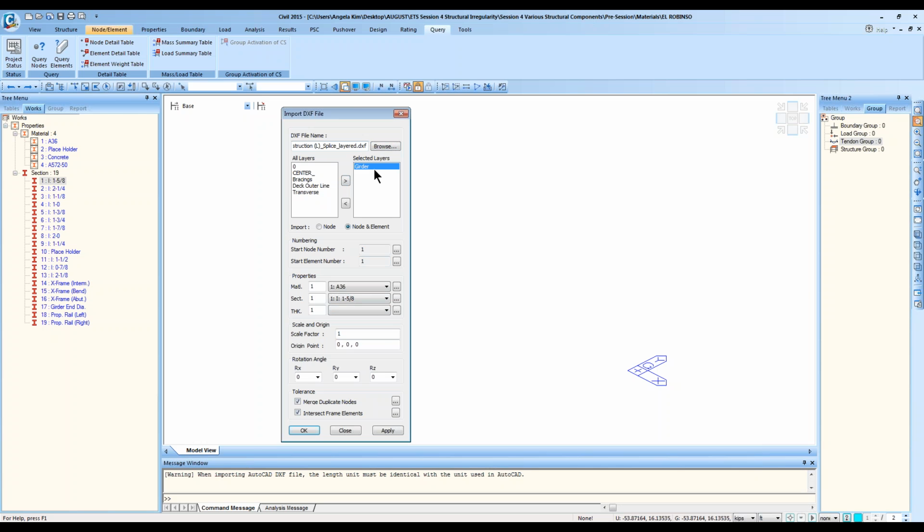Right now, I assigned all the girder sections to one girder layer. However, I have multiple different girder sections. So either in CAD or in Midas, you can take your time distinguishing different parts of the girder with different sections, or you can do the same thing in Midas after just importing them all together as a girder.